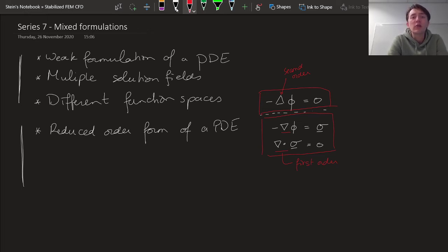And making function spaces that are higher order smooth is typically quite challenging, especially in complex geometries. So if we find partial differential equations that have very high order of derivatives, and examples are, for instance, the equations that originate from shell deflections or beam deflections or phase field models, we typically have fourth order differential operators.